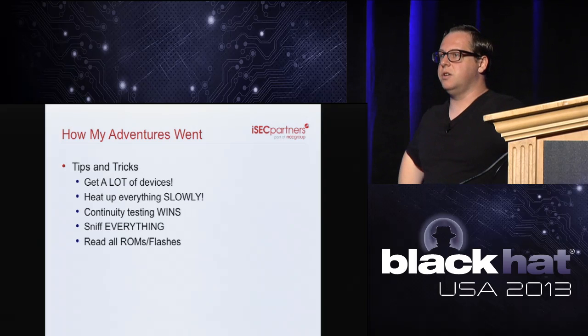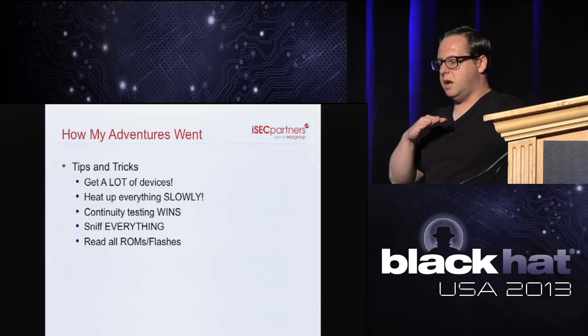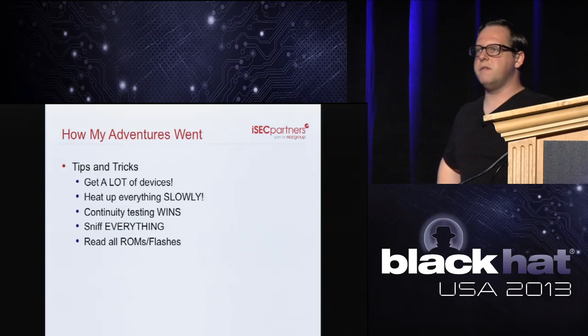Continuity testing: I couldn't have done all of the tracing of this without the continuity testing. It makes it so much easier to trace through boards and planes going through the board. Sniff everything that you find.